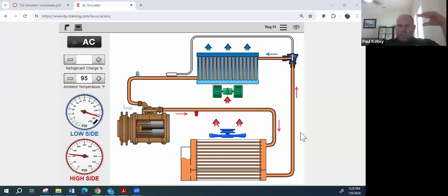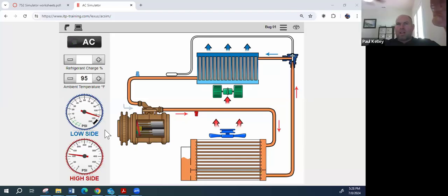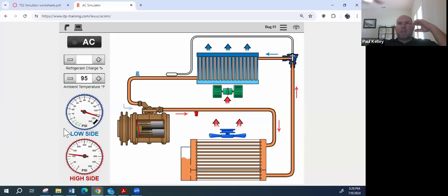So let's just say that it didn't click and we thought it might be low on refrigerant. What would we do to verify the refrigerant level? Well, checking the pressure. Exactly, and we got that. So what do you guys think about these pressures right here? I'll remind you, look at the pressure. What's that, about 110? I don't know. Probably about 105. No, this is over.